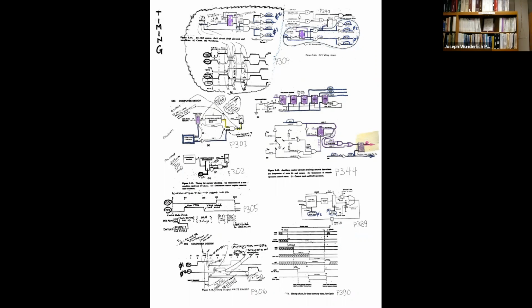developing them, because the reality is, when you create these circuits, and this is what we do inside of IBM, and the whole group, the whole research lab, for System 390 with 2,000 people in it, is we would create the circuits, and then you don't know how fast it will really go until you start just cranking up the clock, and then see when you get bit errors, and then you analyze it and you see what's going on, and you see, well, oh, I needed to not switch so fast here because I had to wait for the capacitance to charge up on the gates on this particular circuit before I had a clock edge come in.